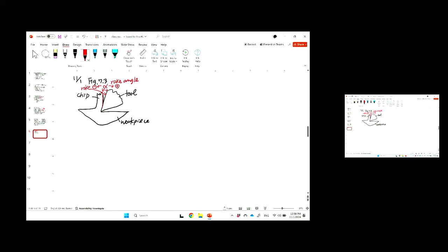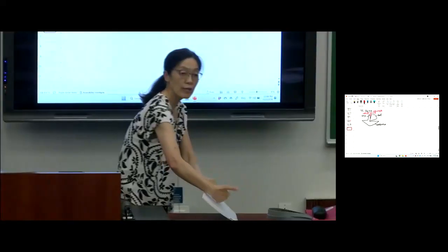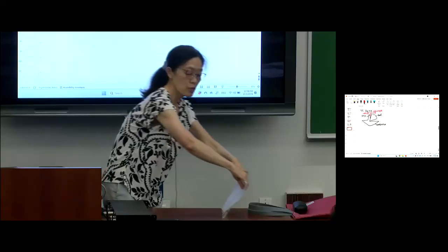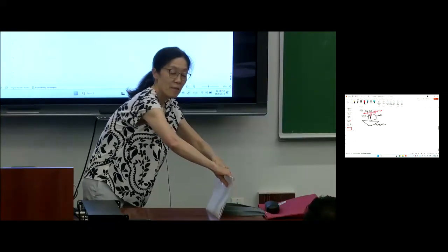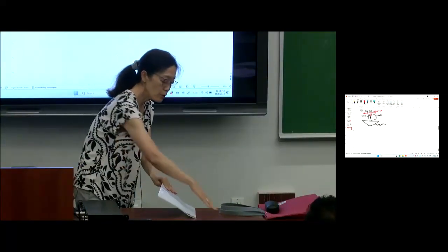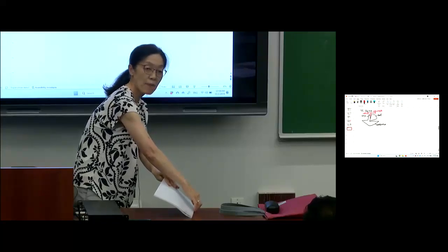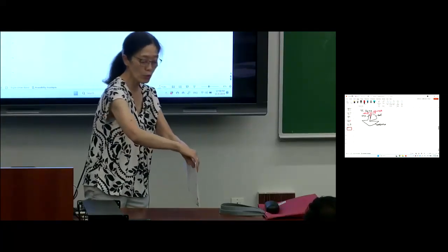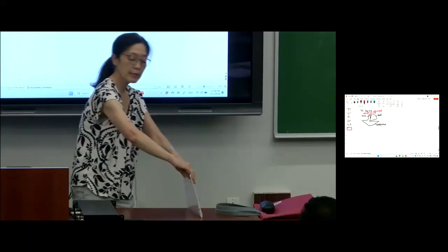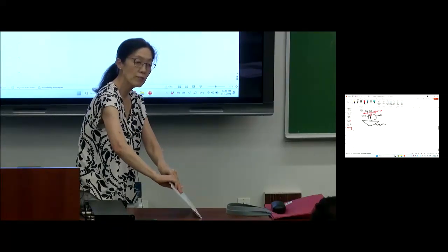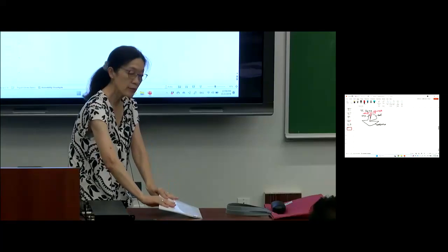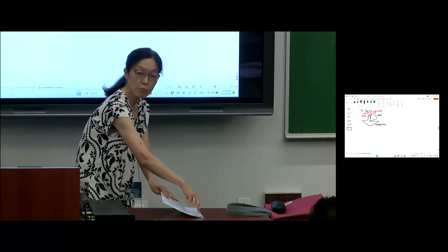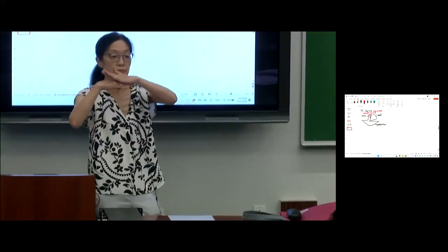Right, let's go this way, right? Your shaver too. So this is the cutter, right? Usually you go this way, right? A little bit of angle, and you don't do this way, right? You can, but go like that, right? Because you are going to keep this cutter sharper, then the chip flows like that. So that's why we call this positive. Usually like 5, 10, maybe 15 degree you can do, because even if you go like that, it's going to maybe chip, right? Be too sharp, right?